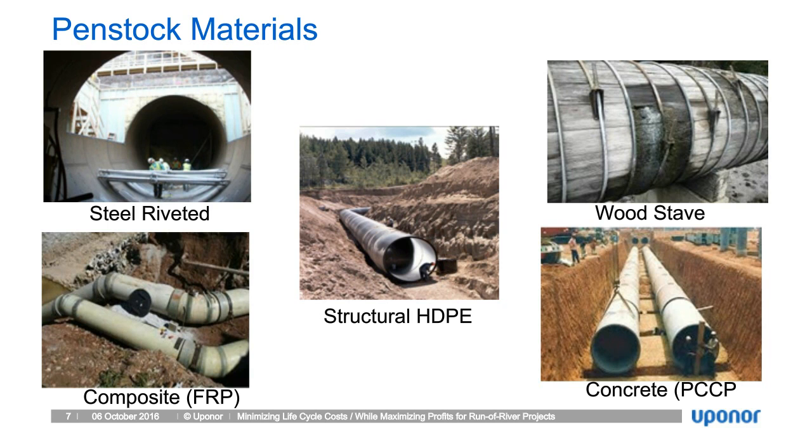Below that is a composite or FRP, which is fiber reinforced polymer, which is a new entrance into the market space about 15 years ago, using typically glass fiber oriented in different directions, so hoop or transverse, which provides the strength, and the glass fiber is impregnated with epoxy in which to bind that together.